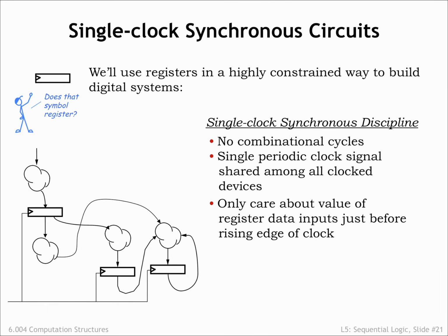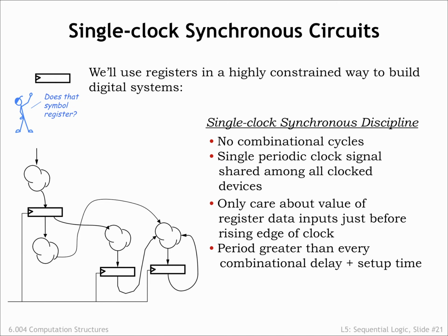The details of which data signals change when are largely unimportant. All that matters is that signals hooked to the register inputs are stable and valid for long enough to meet the register's setup time, and, of course, stay stable long enough to meet the register's hold time. We can guarantee that the dynamic discipline is obeyed by choosing the clock period to be greater than the TPD of every path from register outputs to register inputs, plus, of course, the register setup time.